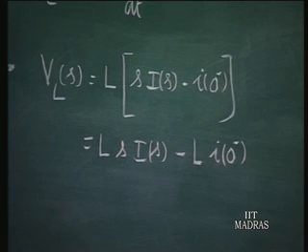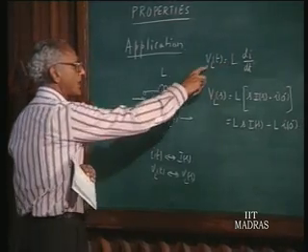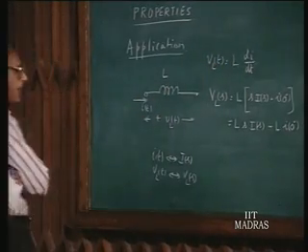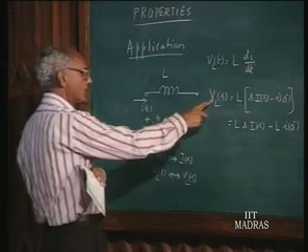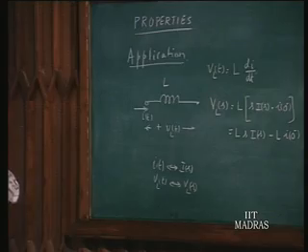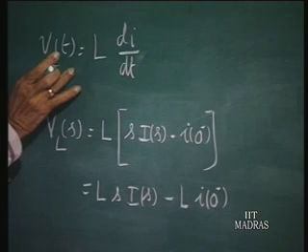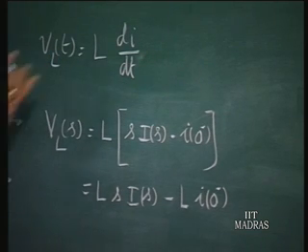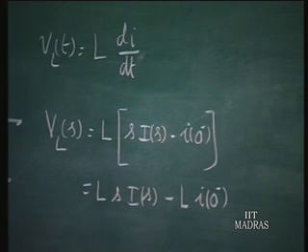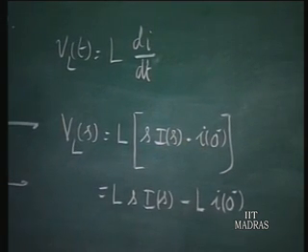Now, two points to be noted here. One, time domain quantities are given lowercase letters vL and i. When we make the Laplace transform of that, we use the capital letters VL(s) and I(s). This is the convention. Secondly, we are interested in finding out vL(t) starting from 0- onwards. There is a possibility that i jumps from 0- to 0+. So, if you want to take the derivative of that current, including the transition from 0- to 0+, then we must take the initial condition here as 0-.